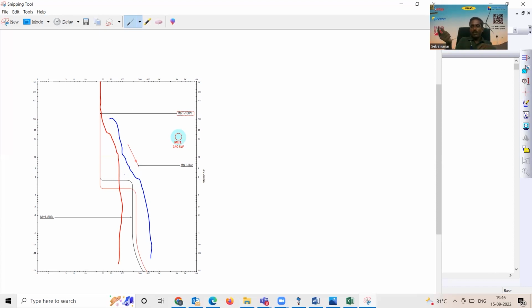You need not really put the variable frequency drive capability in the graph, but what you essentially need to do is add another user defined curve, that is the time versus current curve, which has to be brought into the TCC with whatever starting method is adopted, and this curve you will get in the dynamic motor starting study. This is true except for DOL. Only for a DOL starter, you can rely on the data coming from ETAP.